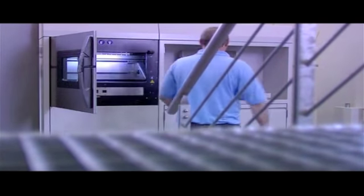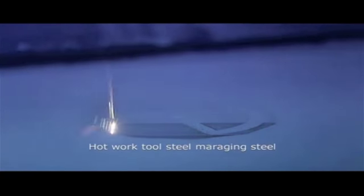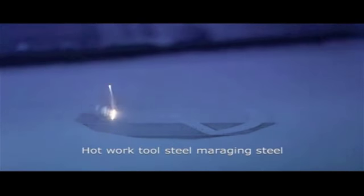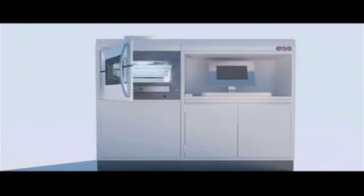Now, the video I'm going to show you is of a specific type of additive manufacturing or 3D printing machine called the EOS M270. This is a metal machine. It actually prints, let's say, in metal. Here you can see you start with a 3D CAD design of the object you want, and you send it to this machine. This machine then takes the 3D design, slices it into layers that can be as small as 20 microns in size.